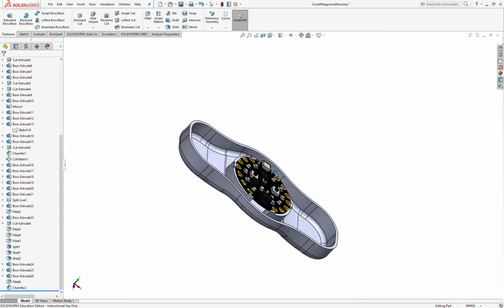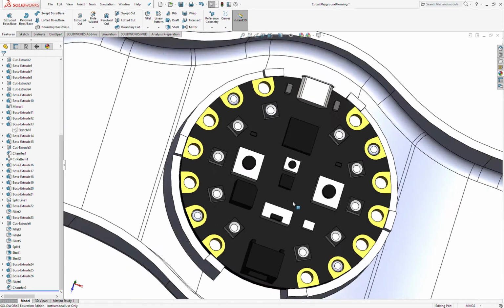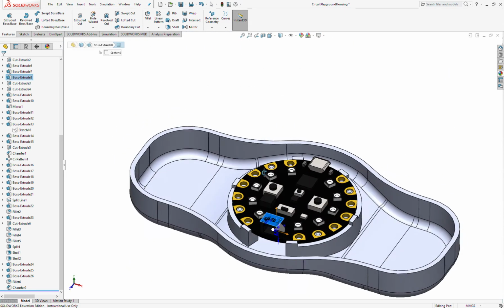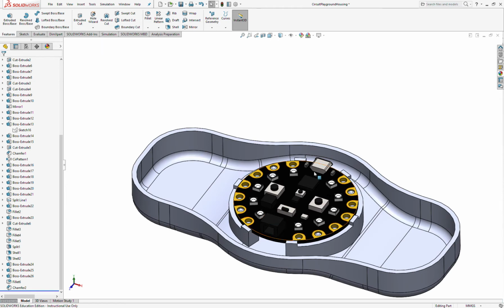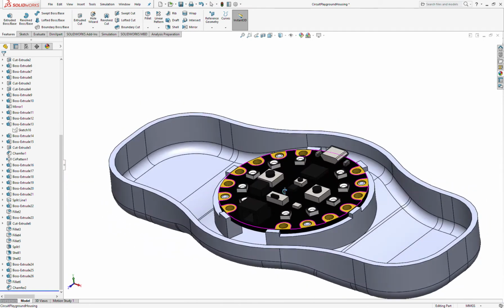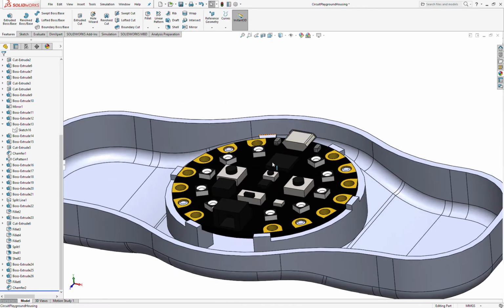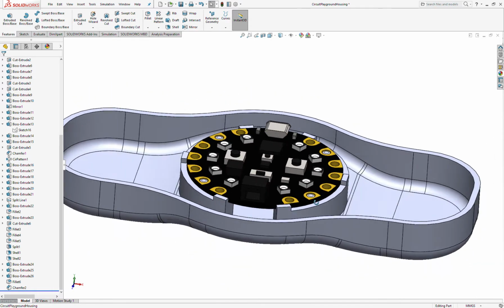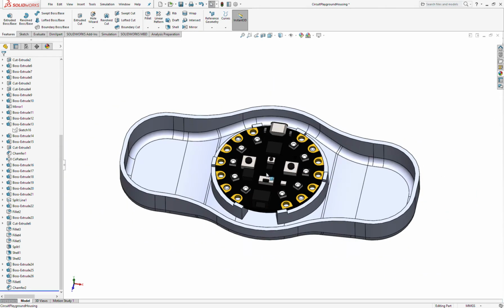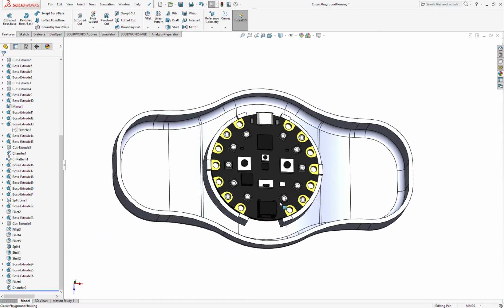There. So now we've got something that's going to hold the board in, these tabs, and these pegs are going to help with the index. And when we put on the cap and it applies pressure here, it'll also help with keeping this down. After we make this first one, we may realize that we need some more pressure points on the board to help keep it in place as well. But that's one of those yet to be seen things that comes out in testing. Once you do this a couple times, you realize what you might need and what you're probably okay without. All right. So cool. So we have some indexing.